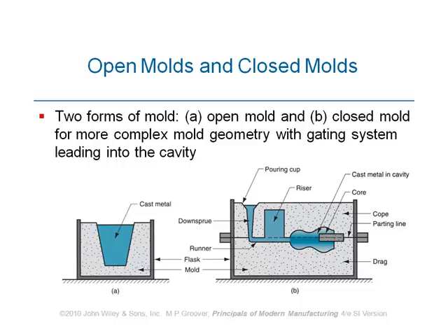In B, we have got another mold which is a closed mold. And of course, this is of common use in industry. The majority of molds which are used in industry in casting processes are closed molds. As you can see here, we have got sand which is tightly packed inside the flask. The sand which is used in this process actually is moist, and it is mixed with a type of binder in order to take the shape and maintain the shape of the cavity.